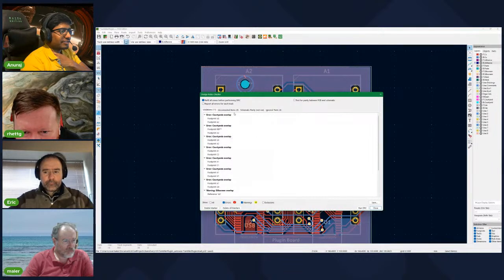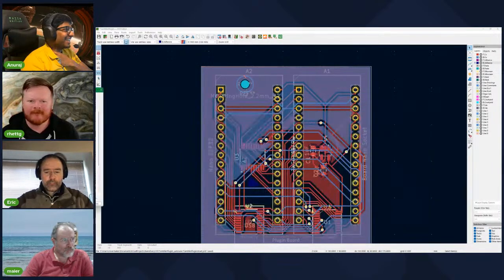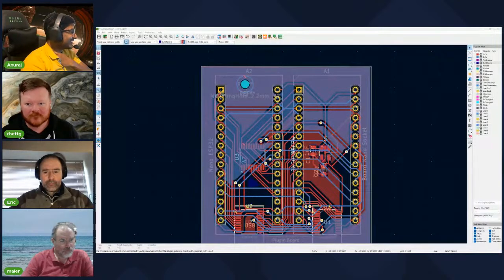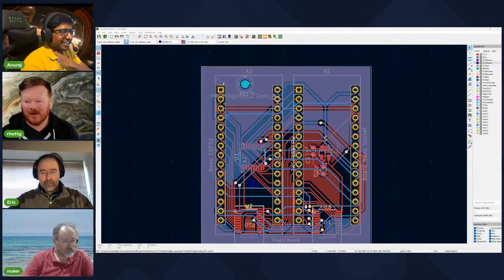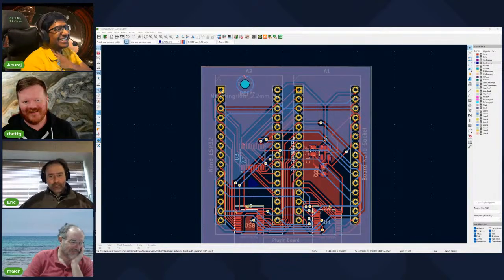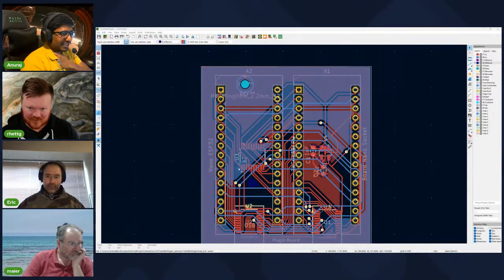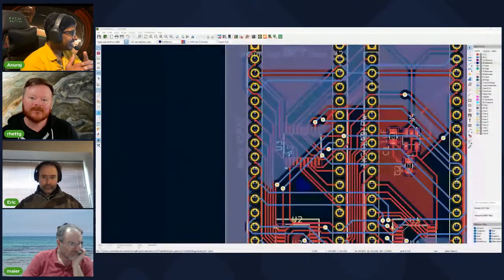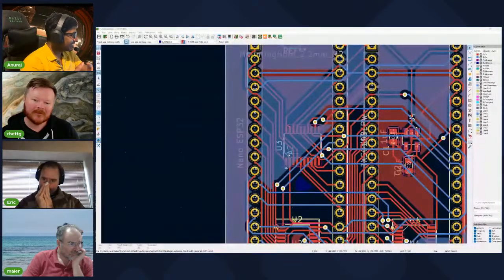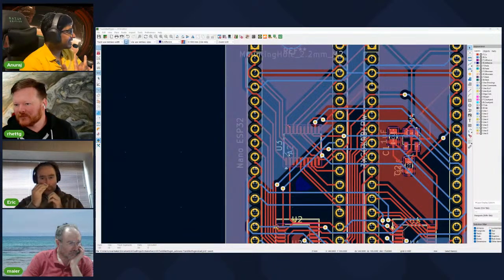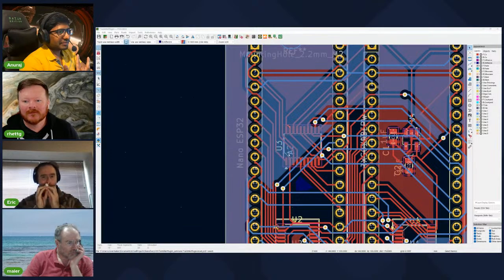What are courtyards? I saw Venkat smiling at this point, and I thought, why is he smiling? Maybe because I ignored all these errors. When you are placing these components, each has a footprint, and there is some tolerance when the footprints and the silk screen are overlapping. I think it gives you some errors. But I ignored all these footprint related errors, because they don't actually affect the electrical connections.